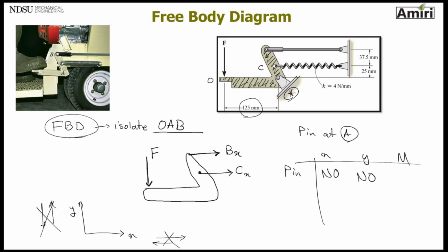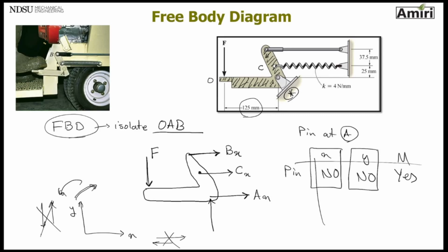And can it rotate about point A? Can it go clockwise, counterclockwise? Yes, that's the whole point of having a pedal, because it can rotate. So it's a yes. I don't care about yeses. I care about no. Whichever you see a no, put a force there. So I'm seeing a no in X, I'm going to put an AX. I see a no in Y, I'm going to put an AY. And this is my free body diagram for this pedal.